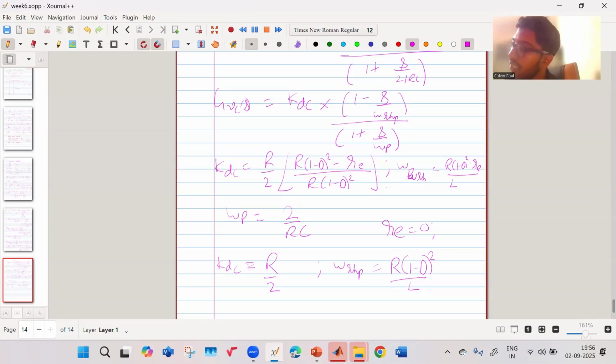So now, what I'd like to point out is this is actually a first order system. This GVC of S for current mode control is first order. What it is doing is pushing your inductor dynamics to a very high frequency. So your inductor acts like a controlled current source. That is the advantage of current mode control. It makes your dynamics first order, and that is very useful. It becomes easier to design a controller for current mode control.